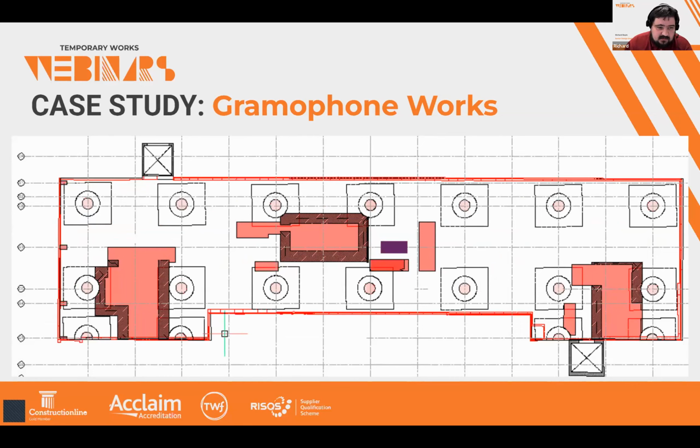So in the top on the second one, you can see that there's a riser just coming out of the middle core there. That will cause an interrupt from the middle, but from the top, the load will just reorientate round that hole. So that wouldn't have been a problem for that location. But these large holes needed some thought about how we were going to support this load path.